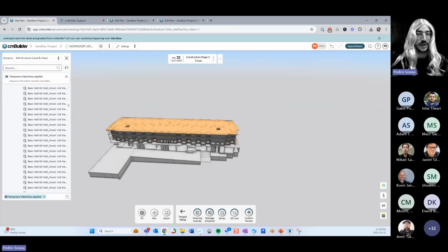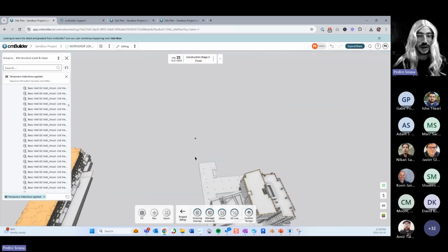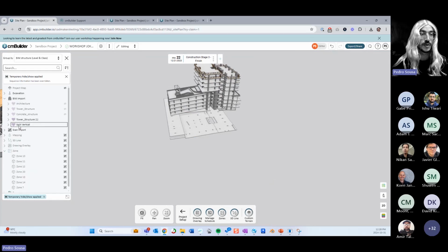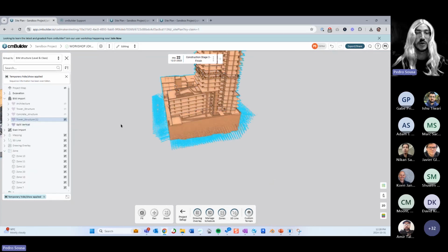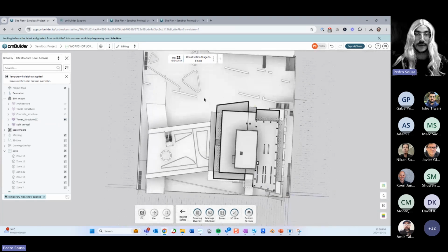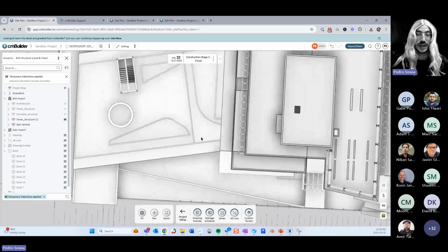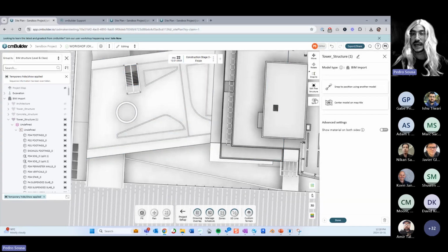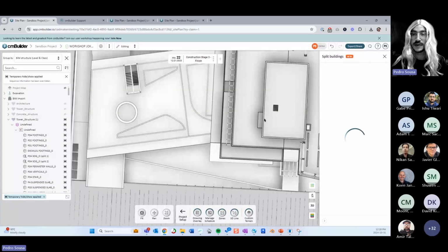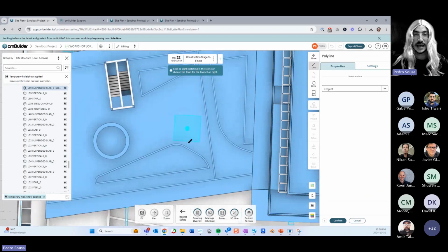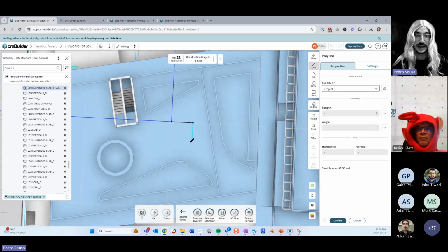Cool. Another big use case for this tool is to create openings for cranes, right? So if I show this whole model over here, and I want to create an opening for a crane, let's say at this location or maybe at this location, I simply continue with my split, and then I can add a split geometry again over here. From this point onwards, I'm going to create a line, and from this line, I'm going to draw a closed shape that represents the opening for my crane.